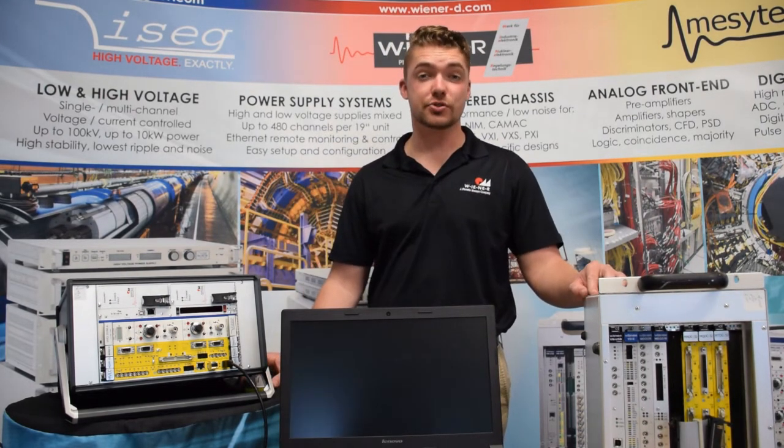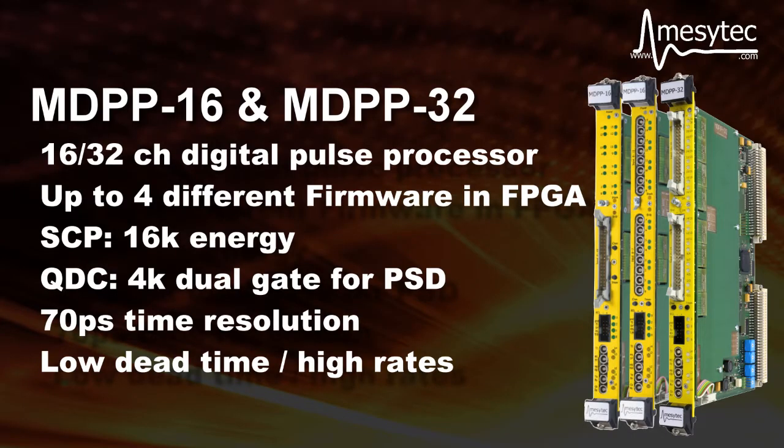So what readout modules are available from Mesytec for this system? The new MDPP16 and MDPP32 digital pulse processors, which combine easy-to-use interfaces and high-resolution rate performance. The MDPP digitizers were developed to directly accept any preamplifier or detector signal for wide ranges of detectors. The digital pulse processing is performed with an FPGA with selectable firmwares to allow best pulse processing for the individual detector type.